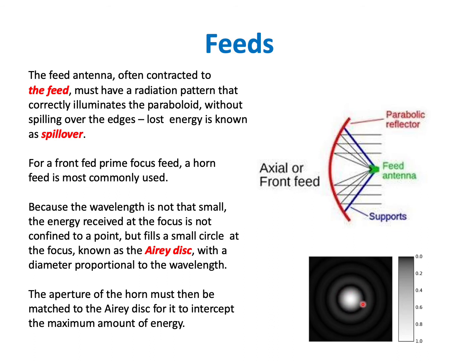Now this is known as an airy disk. So actually you can see also some artifacts, some rings around that airy disk. So what we want to do is tune our feed to perfectly intercept that airy disk so that we get all of the power that's included in it without getting any of these artifacts around it.